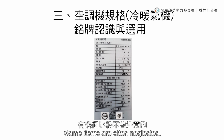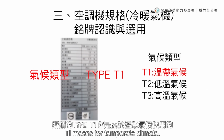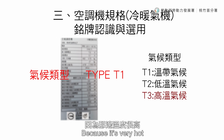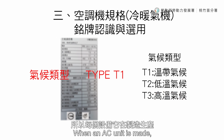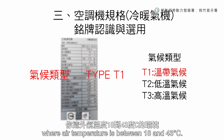Some items are often neglected, like this one, type T1. T1 means for temperate climate. If you use this unit in the Middle East, it wouldn't work because it's very hot. Cooling efficiency will be low. When an AC unit is made, T1 is meant for temperate climate, when the air temperature is between 18 and 43 degrees.